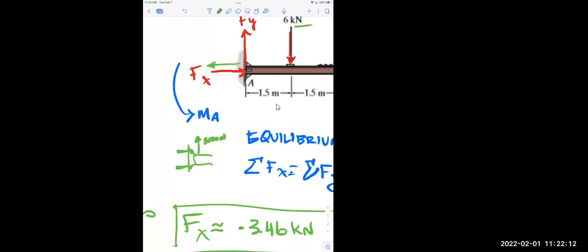We'll talk about this more later in this discussion, but notice the bolt's not being pulled on lengthways. It's actually trying to be sliced in half like a set of scissors. So the part's stuck in the wall, but this thing's going to push up in the air. I could just shear those bolts right off, slice them off perpendicular to their length, if you will. That's what a shear force is. So again, I got to have enough bolts. That's not going to happen.